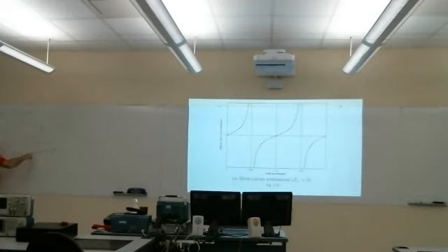Now, for our right propagating wave, remember we've always had e to the minus j beta z for this first term. But now z is minus L, so that's why this appears as a positive term. That's the numerator. And then we had an expression for the current. It's similar, except we're subtracting the second term because the current is going to our left, and it's divided by the characteristic impedance of the line to get the current.